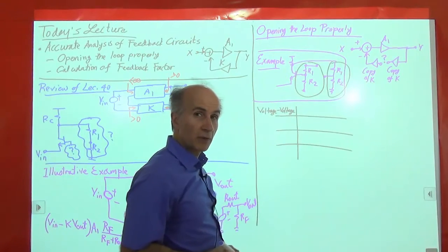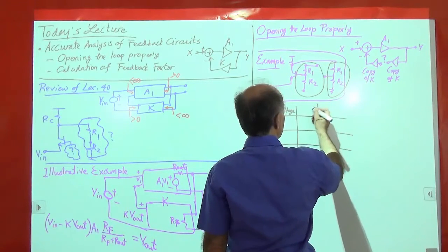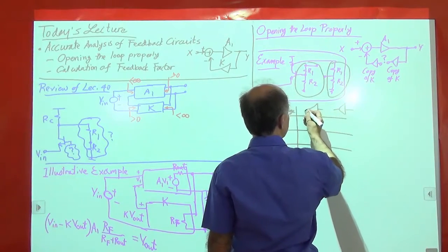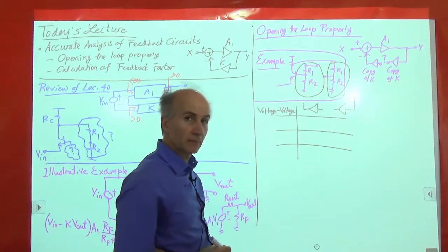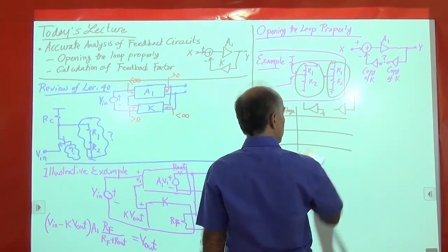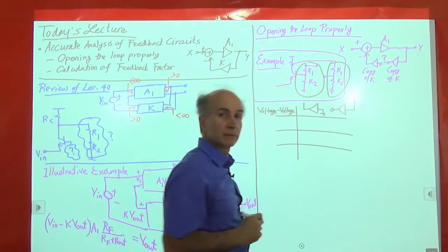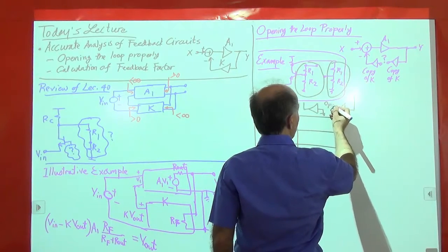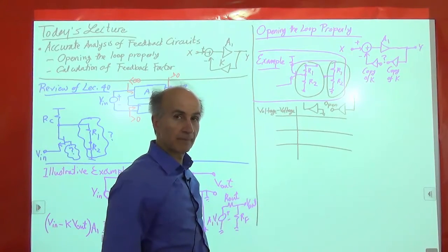So for voltage feedback, this is what we have to do. We draw those two copies. This goes to the input, this goes to the output, right? And this will be AC grounded, and this will be left open. So this is open circuit. I'll just write open here so that you know it means open circuit. It doesn't connect to anything.